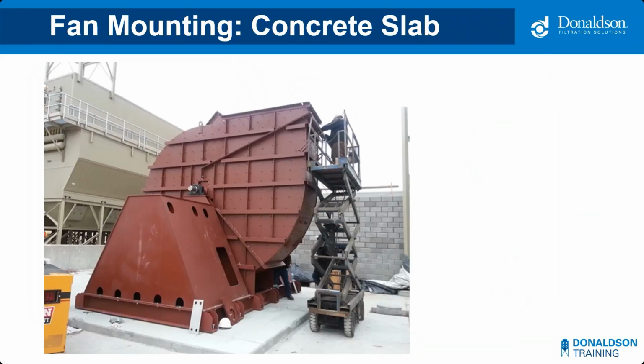Here's another great photo, another textbook installation. This is a pretty sizable fan, but again, the takeaway here, fan mounting, putting this on a concrete slab is the preferred method. That gives us a great inertia base and provides a fantastic foundation for a big fan like this.